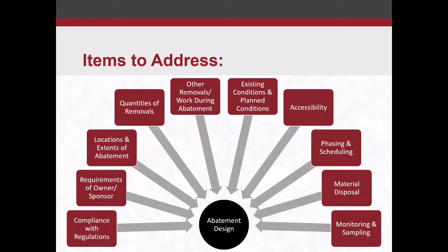in its own right. But then you add in the factor that you're doing abatement and you've got a contained, controlled work area with polyethylene sheeting all over everything. What do you have to poly? What do you have to clean? So you're bringing in lifts. Those lifts have to be cleaned and all that good stuff, or protected. So those are things you want to make sure the abatement contractors are aware of.